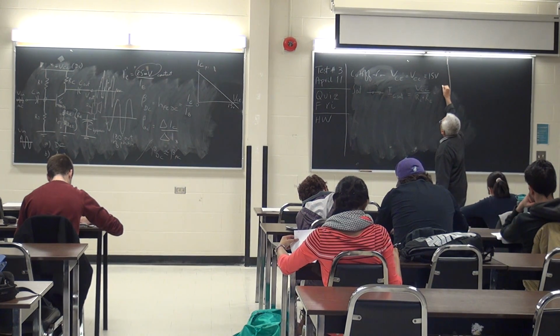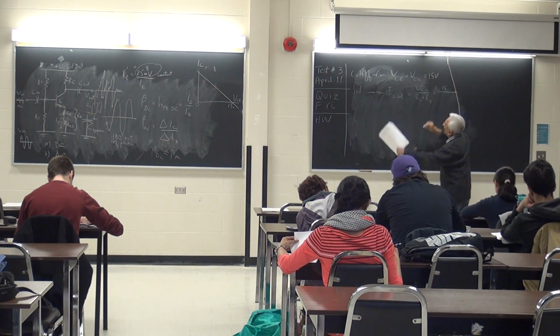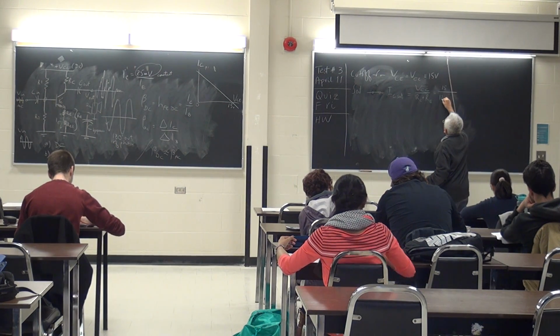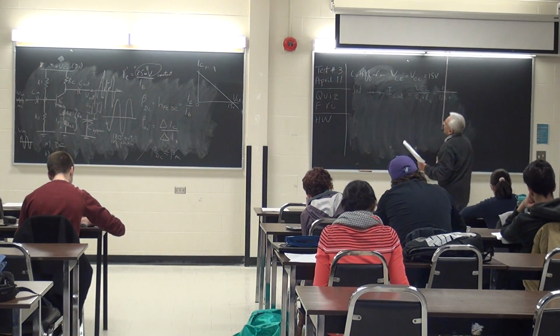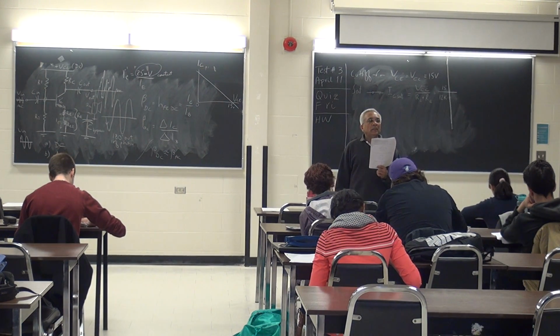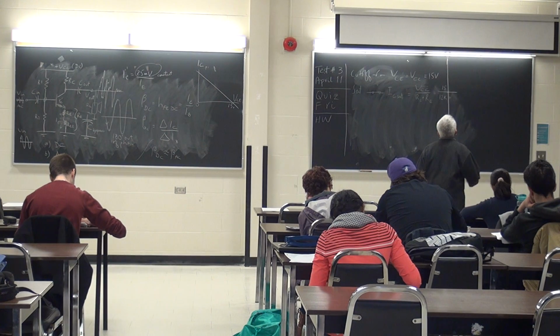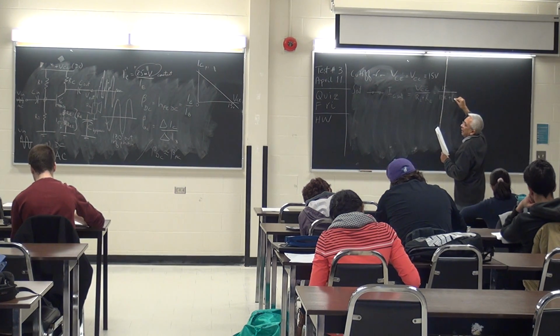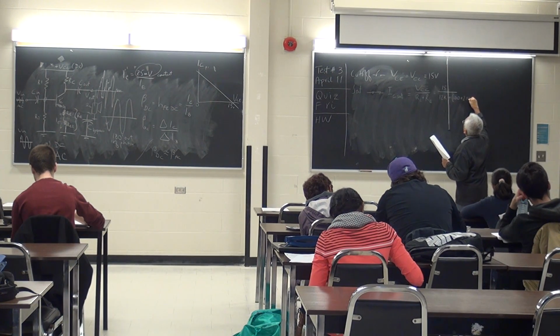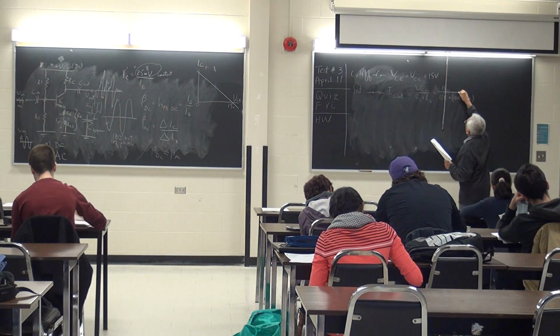So is that 15 over, how much is RC? 12K. How much is RE, which is RE1 plus RE2? Is it 100 plus 2.1K? 2.2K?